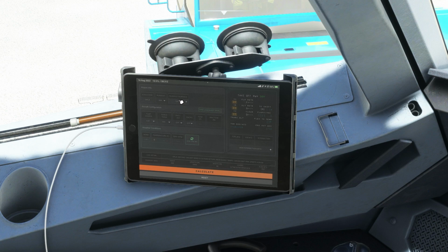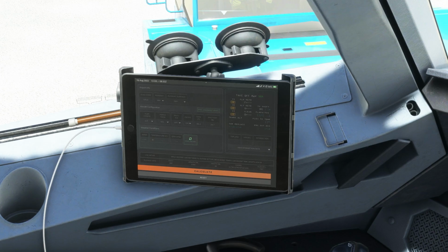Okay. Runway surface is dry. Flap configuration 1+F, as I've told you before. Forced TOGA, yes. Packs is basically your air conditioning. I will be taking off with the packs on. Once I sync the load sheet, it will get the takeoff weight 66.2.